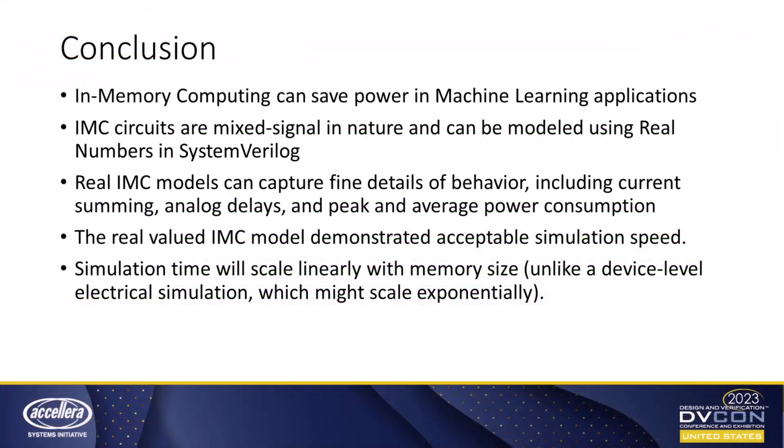In this video, I've tried to present a case that in-memory computing can save power in machine learning applications. I also tried to make the case that IMC circuits are by nature mixed signal and therefore can be modeled using real numbers in SystemVerilog, and that those real number models of IMC circuits can capture very fine details of behavior, including any current summing behaviors, analog delays, also peak and average power consumption.